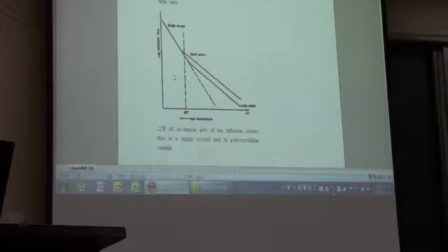Because if you add copper beyond the solubility limit, then we are going to have a precipitation, and this precipitation will happen on these triple points and grain boundaries rather than the intergrains, because the grain boundaries are unstable sites, so they have a high potential to form a precipitation.